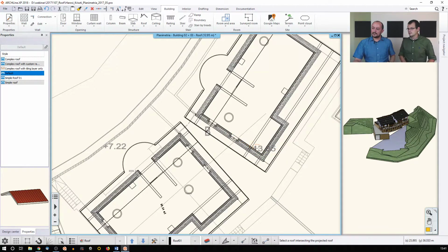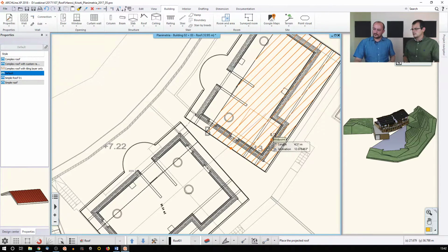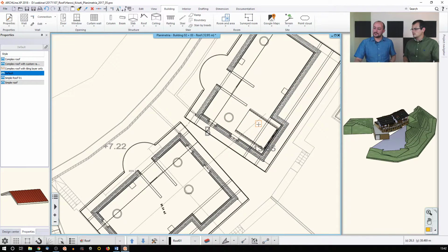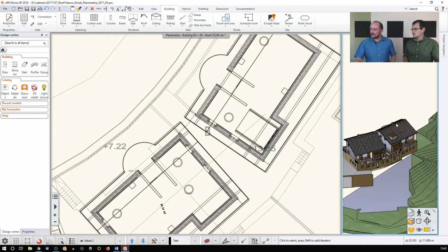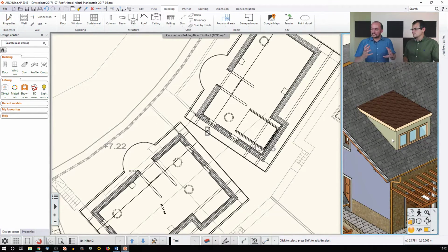And then I need to click on the roof plane itself. Now this roof has a very small plane and this large plane, but I don't click inside the area, because I need to select an edge of the roof, so I click on the side or the bottom or any edge of it. Now the software understands that this is the roof plane, and I'm able to position it somewhere. Let's say I'm about to put it here. The software creates the walls, the roof, and everything else, and now it's there. So this complex shape, which would otherwise be a bit difficult to draft, comes down to properties: the thickness of the wall, the number of windows, the pitch of the roof, and the shape of this roof.